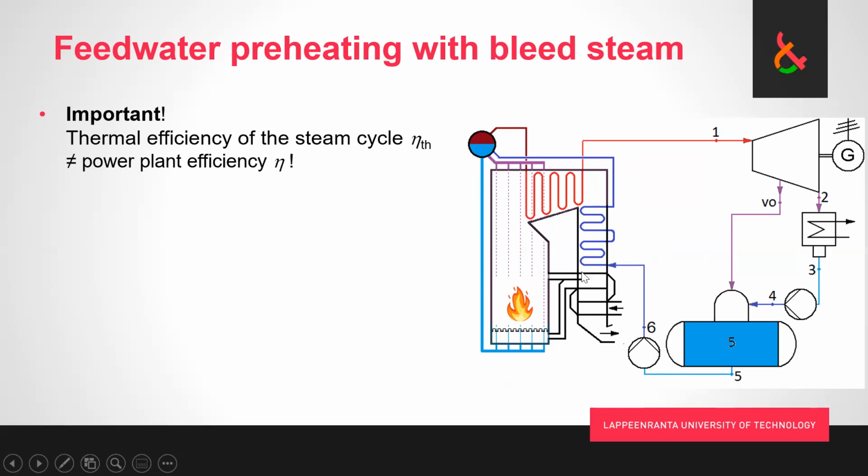Now in a normal boiler, the hot flue gases go here, they're cooling, cooling, cooling, and then the last heat exchanger surface in the back pass that they meet is the air preheater. With the cold air going into the boiler, we can cool the flue gases pretty much as cold as we want in most boilers, but there are a couple of exceptions.